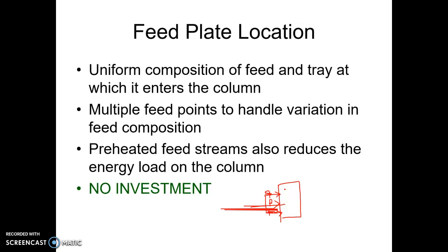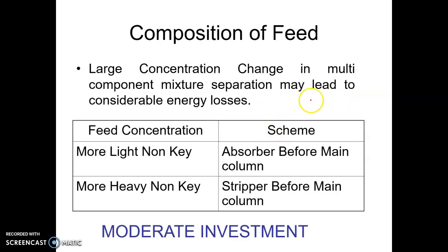Preheated feed streams also reduce the energy load on the column, which I think we already discussed, so I don't think that needs to be discussed. It is written no investment. However, no investment once the plant is already erected. Very slight investment in terms of providing additional piping and valve for the feed.